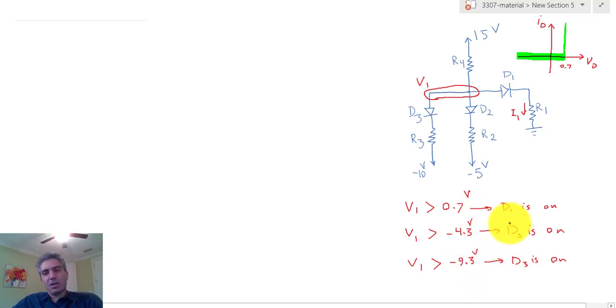And that gives you a lot of information in terms of how to make assumptions about the operation of the two diodes. In other words, if you only have one diode in the circuit on, that could only be D3. That's a pretty good information to have.